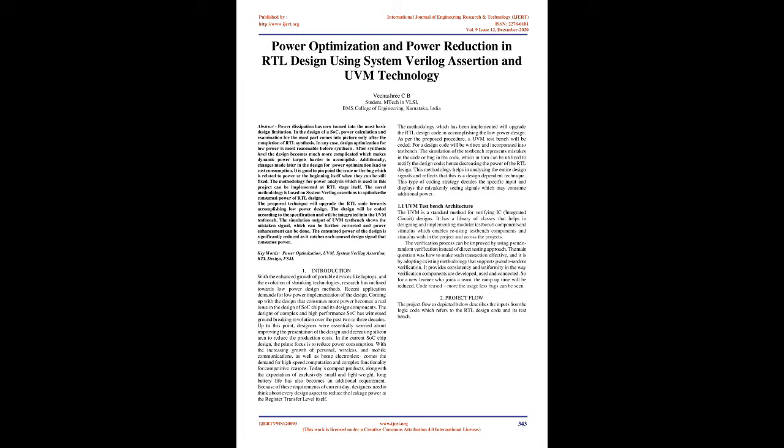In the design of a SoC, power calculation and examination for the most part comes into picture only after the completion of RTL synthesis. In any case, design optimization for low power is most reasonable before synthesis. After synthesis level the design becomes much more complicated, which makes dynamic power targets harder to accomplish. Additionally, changes made later in the design for power optimization lead to cost consumption.